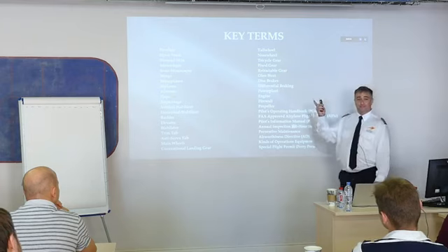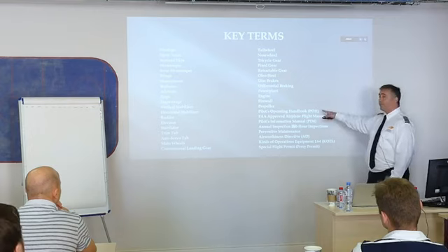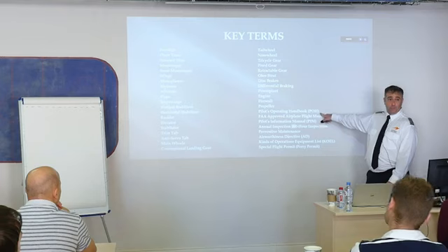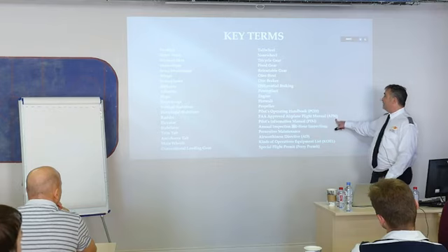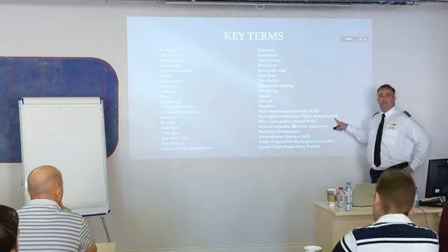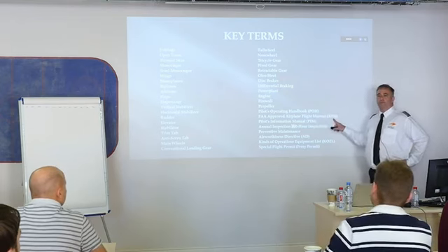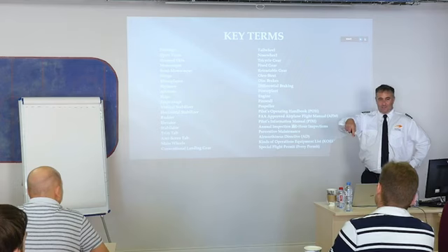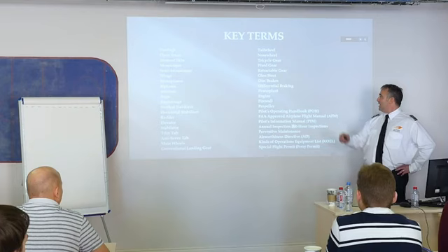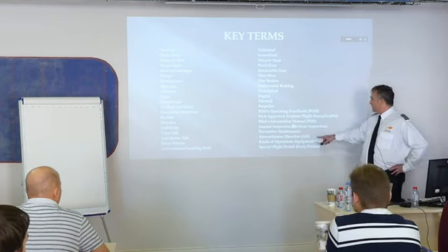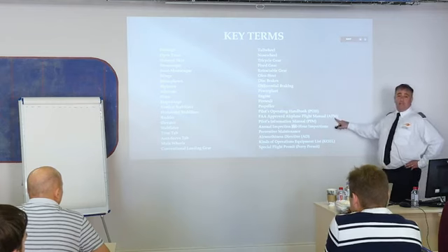All right. Disc brakes. It's another one of mine. Differential braking, power plant, engine firewall, propeller, pilot operating handbook. That's a part of the airplane equipment that has to be in the airplane. The airplane flight manual. Difference between these two, you'll see this a lot: AFM/POH. The airplane flight manual is for that exact airplane. So that's registration 41 Mike Echo. That's registration 737 Bravo Alpha, whatever it is. All of it is for that exact airplane.